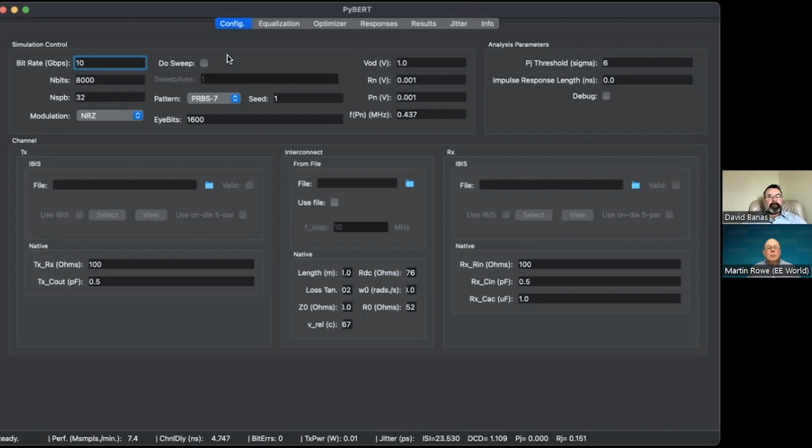It then allows you to define several different combinations of parameter values that you want run. And then you can go away and have a cup of coffee and chat with your colleagues while pyBERT just cycles through all those and prepares the results for you. Okay. And then you've got a choice of bit patterns that you can simulate. You've got PRBS, that stands for pseudo random bit sequence, and you've got the 7-bit version, the 15-bit version, the 23-bit version. Those are the three most commonly used in serial comm. That's why we've coded them up. Sure. And for this, I think that's probably all you need. That pretty much does cover everything.